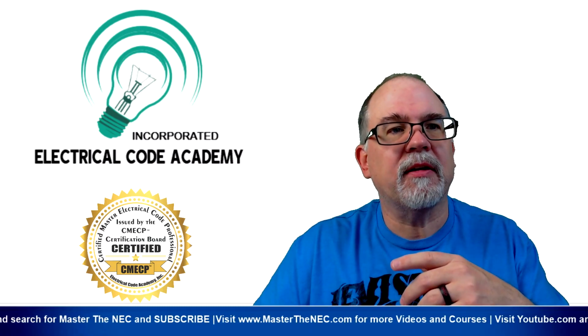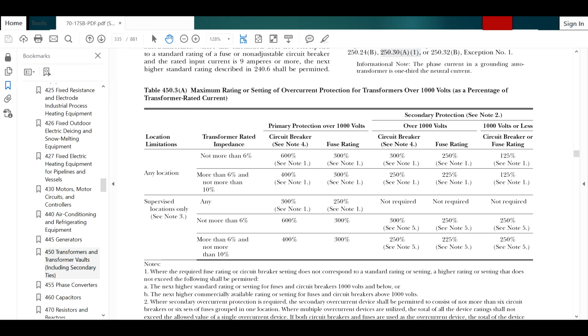All right, so let's go down and look at the code and try to understand what we're dealing with. So dealing with the location limitations for this overcurrent protection and the transformer application, it says any location. Where the transformer is rated not more than 6% impedance, then the primary protection can be up to 600% of the primary transformer rated current. If it's a fuse that's being used for that primary protection, it can be up to 300%.